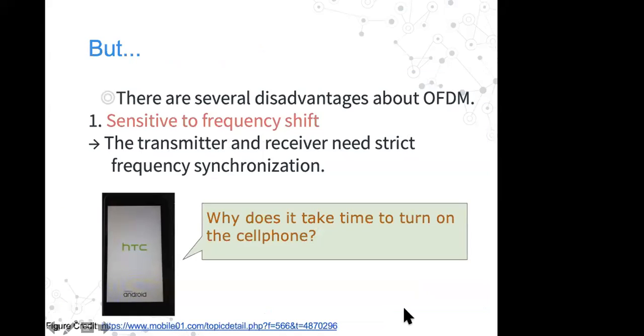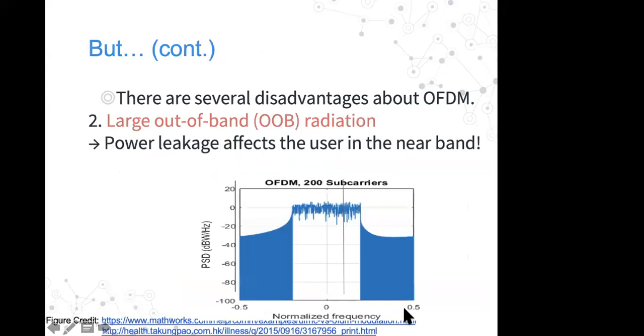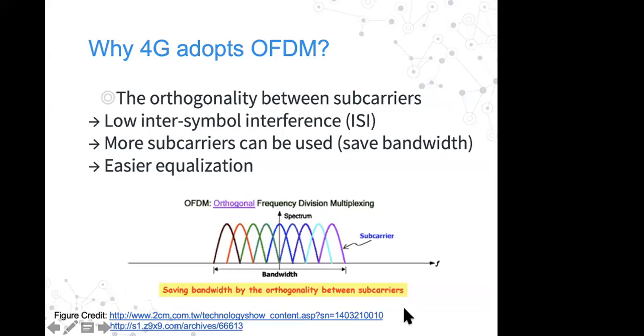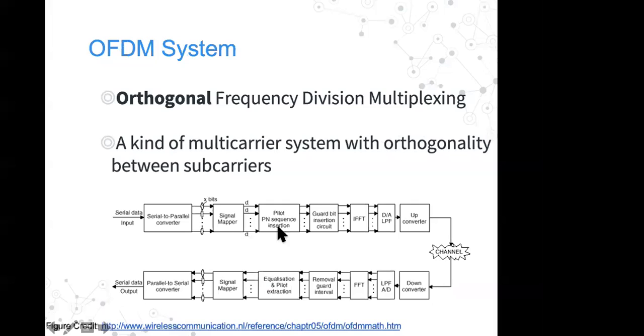So what is the main disadvantage in OFDM? If I ask you what the main disadvantages are, it is the orthogonal carriers, right? IFFT and FFT. We are designing this IFFT block and FFT block. Suppose the IFFT block is generated with different multi-carriers, that is with sine 2 pi f naught t, f1 of t, f2 of t, f3 of t, and so forth.